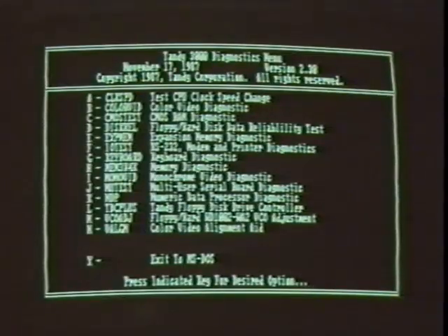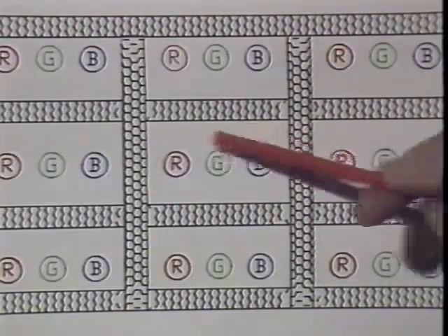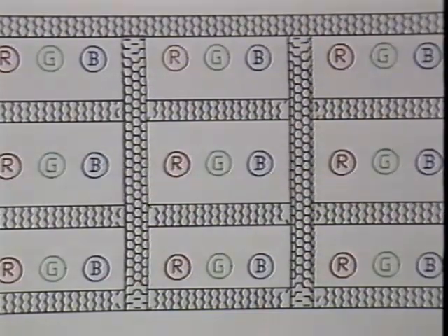There are several external parts of the CRT that you will need to recognize. The first of these is the face. This is the part of the CRT on which the data is displayed. The inside of this surface is coated with phosphor, a material that glows when struck by the electron beam. Monochrome CRTs have a smooth coating of a single type of phosphor. The type of phosphor used determines the color of the screen and its persistence, or how long it glows after being struck. Color monitors use three types of phosphor arranged in groups called trios. Each type of phosphor glows in one of the primary additive colors, red, green, and blue.